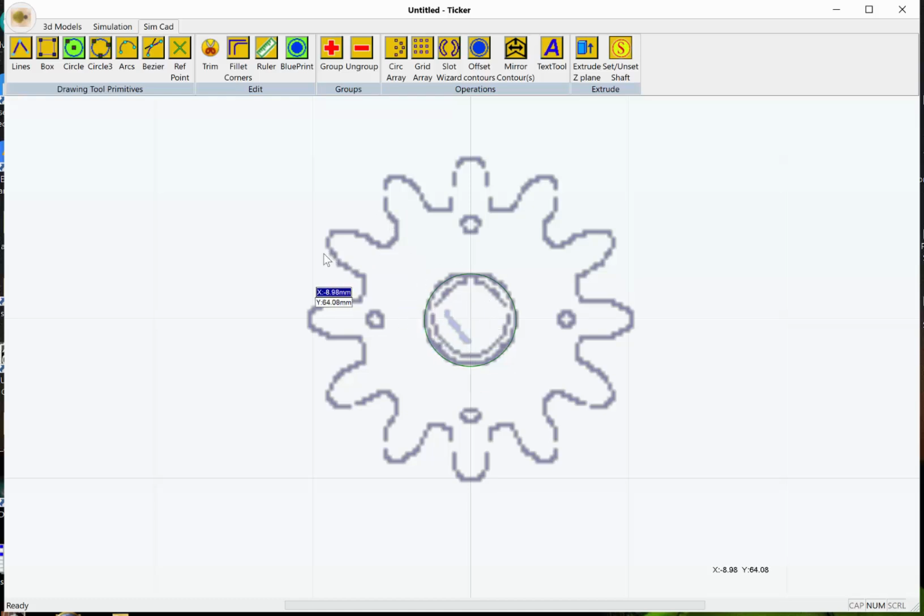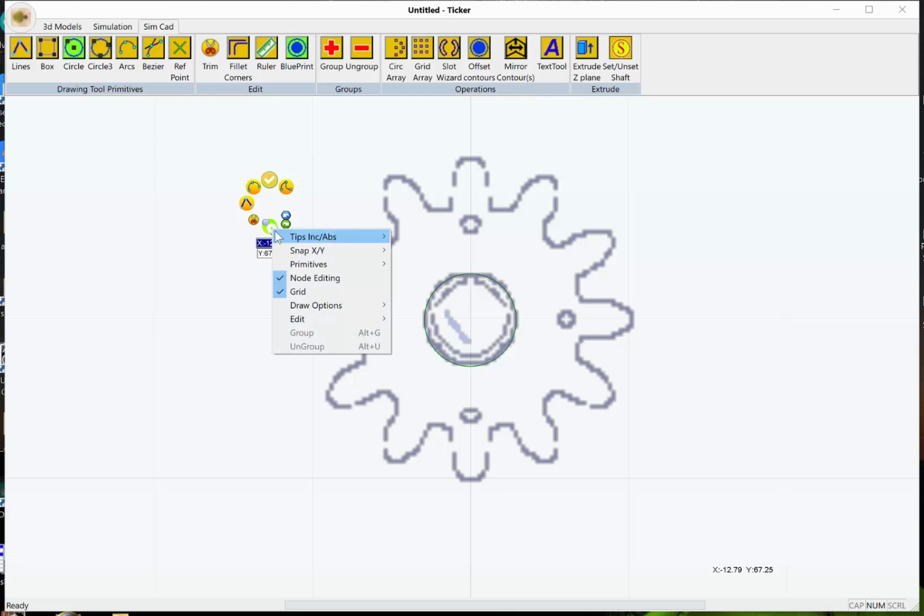But if we were to be picky, let's look at how the drawing works so that we could make that more exact. At the moment, I have a circle tool selected. You can see the circle is highlighted up in the corner. And there is a context menu on our right mouse click. And it has several selections that you can use. Down here in the bottom, we have undo and redo in case you make a mistake and you want to back up. At the bottom is a gear that you can click to turn on several options, such as a grid, snapping distances, and so on.